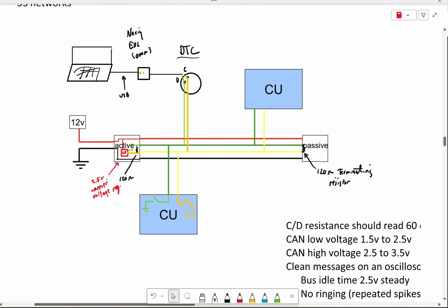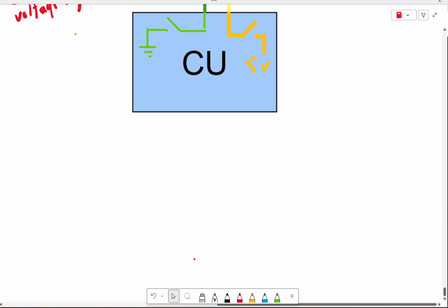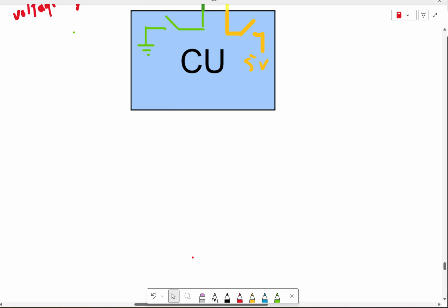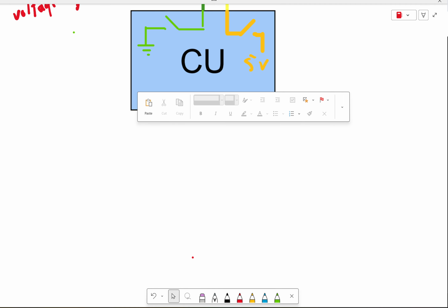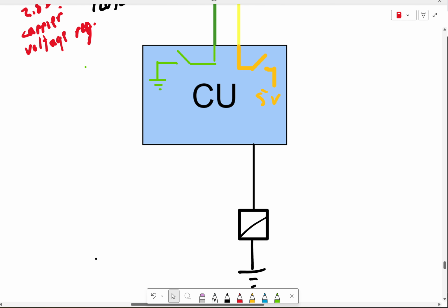This is coming from the diagram that we were looking at yesterday. We already had the CAN bus drawn in here. Now we're going to take a look at some inputs and outputs to the controller. So for outputs, we'll start with a simple solenoid here. Okay, solenoid or relay or whatever. This is just a coil of wire, and we're going to ground it. But what that would mean is that inside the controller, we're probably connecting this to, let's say, a 12-volt source.